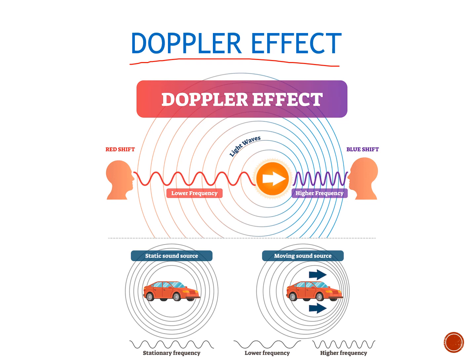If you remember, if this is the source of the signal and it's coming towards us, then the received frequency is slightly higher than the actual frequency. And if it's moving away from us, like in this case, the received signal frequency is slightly lower than the actual one. So based upon the distance and the movement of the receiver, the frequency will be different. Now you can see it would be very difficult for the receiver to track these changes and have a local oscillator of the same frequency as the modulator.